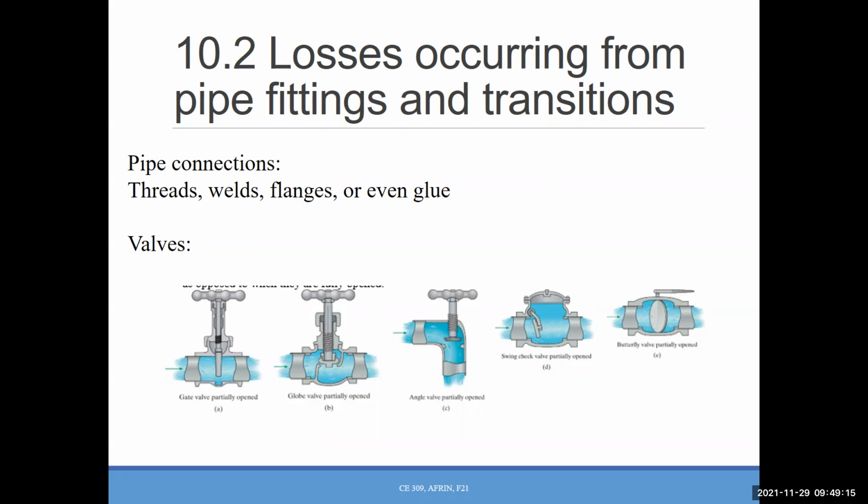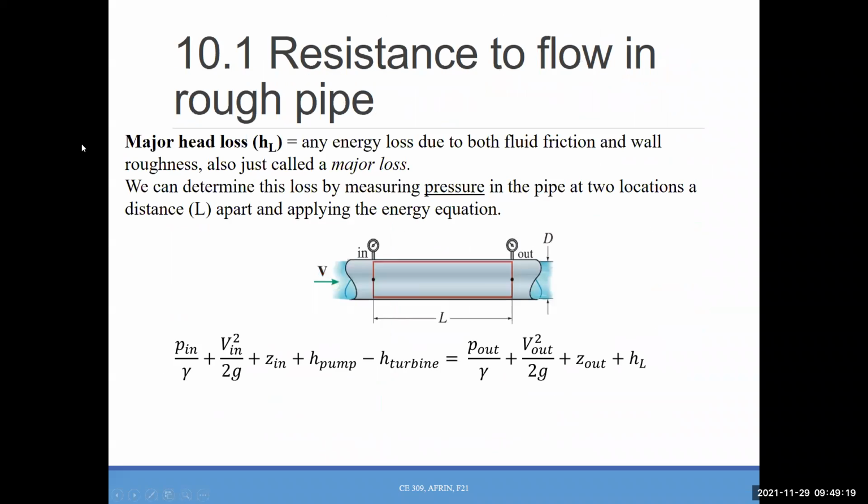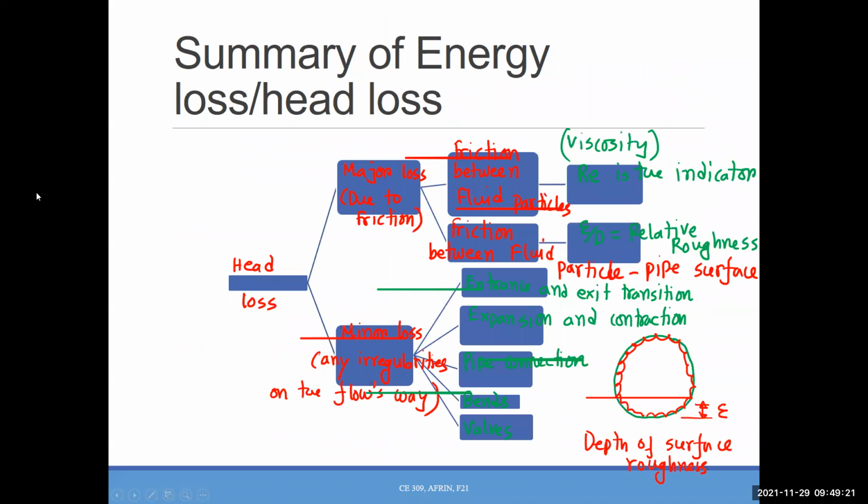Okay. Just one more thing. Go back to that summary table here. Just write down two things, then this summary table will be complete. So the major loss, F L over D V square over 2G. And for the minor loss, this one is KL V square over 2G.